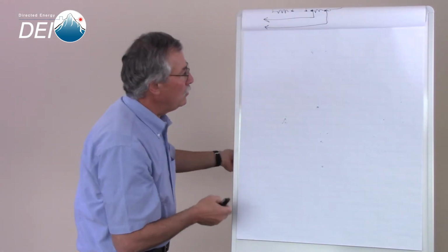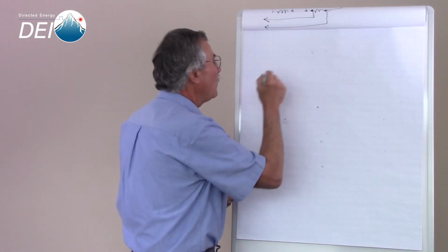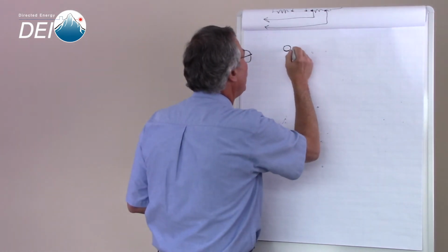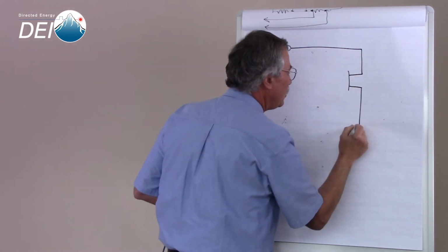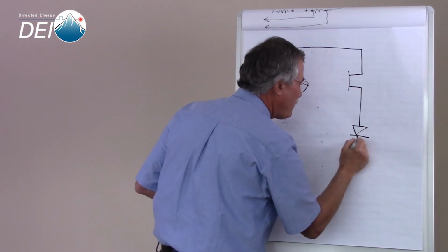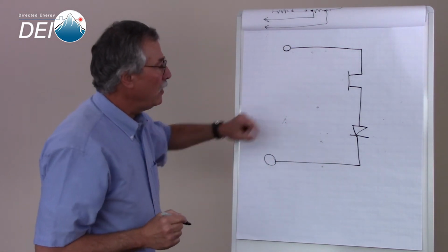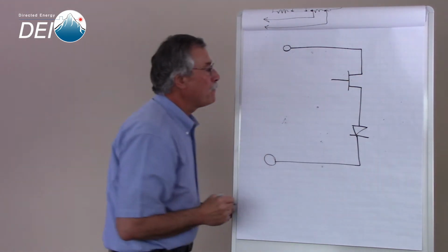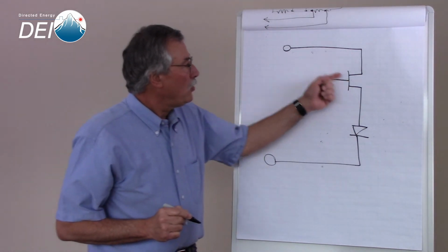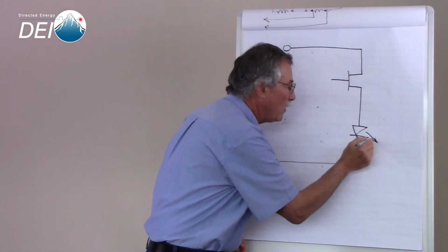There is another issue that I'd like to bring up that's important on large laser diode drivers when it comes to safety. A lot of our laser diode drivers are controlled by a switch, and we'll just say this is a voltage source of some sort coming out here. When we turn on the switch, we run current through the laser diode, and we get light.